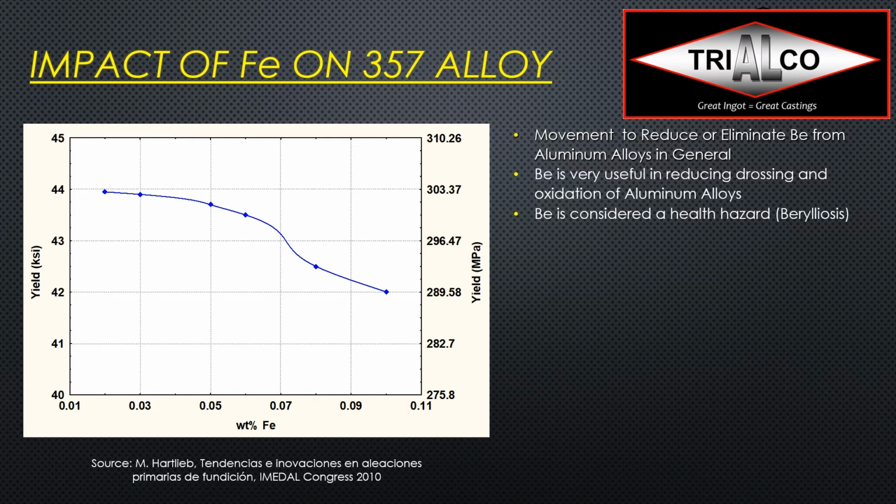So we're coming usually from a primary version of, let's say, a 0.10 or a 0.11, and then we reduce the iron content, and we can see going down to 0.08 already increases it quite a lot. But if I go beyond that and go down to a 0.06 or a 0.05, I'm gaining a real lot. I can gain almost 10% by going from a typical 0.12 down to a 0.03 iron level. And that is a very useful thing to know.